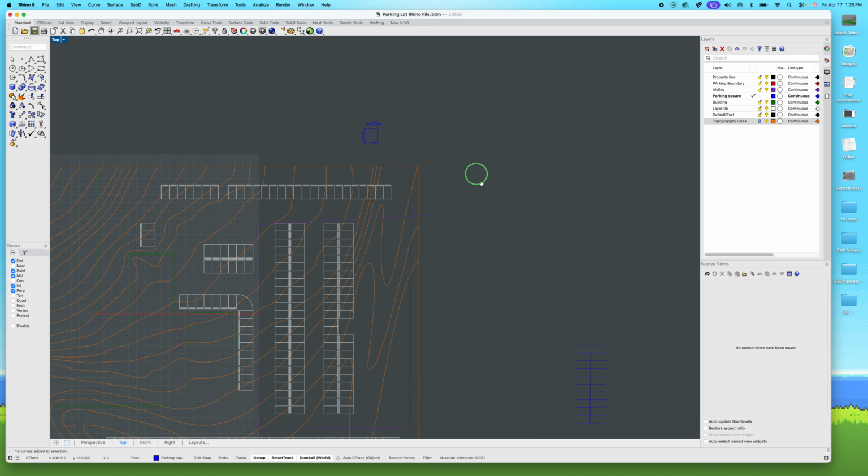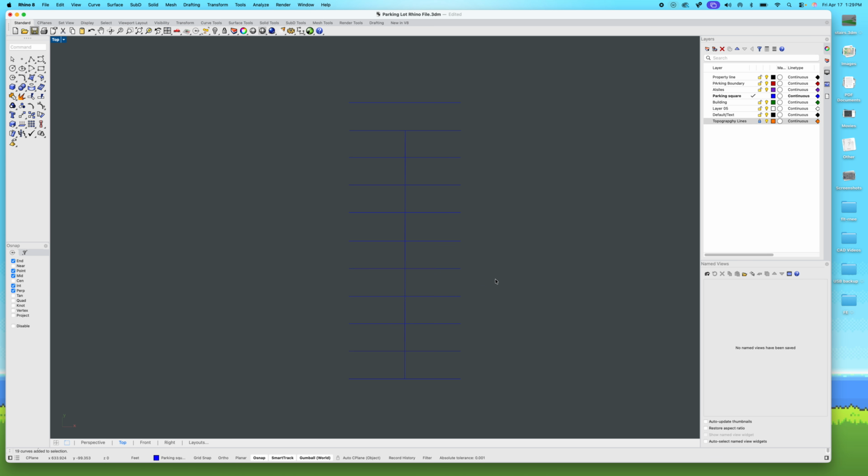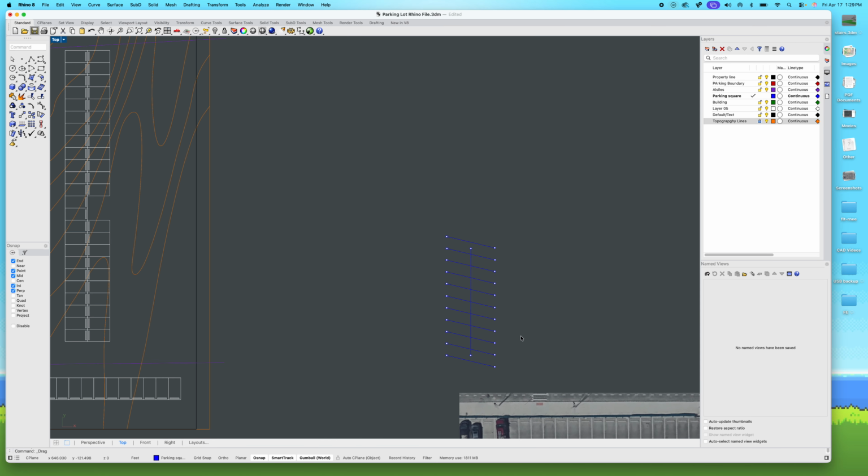Good question. You can also draw it, right? You can also skew it. So for instance, if you highlight any line and you do function F10, you can actually take the points and move them as well. So for instance, if I wanted to angle them, voila, right? Again, kind of fake it till you make it.